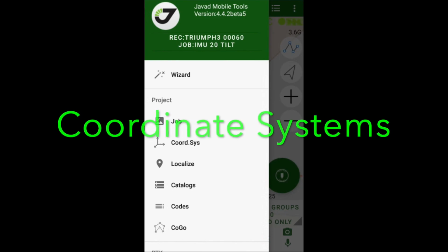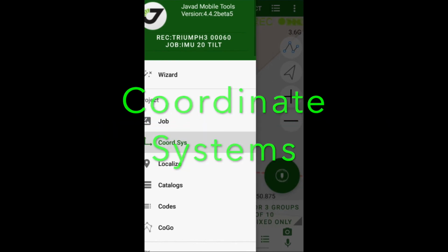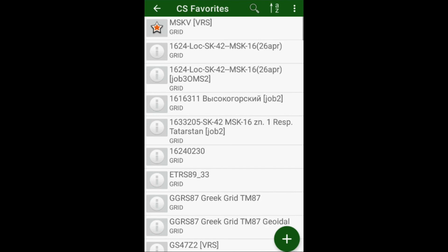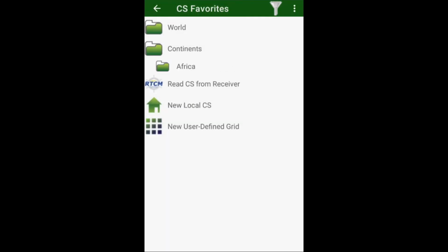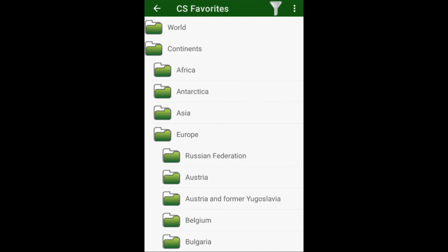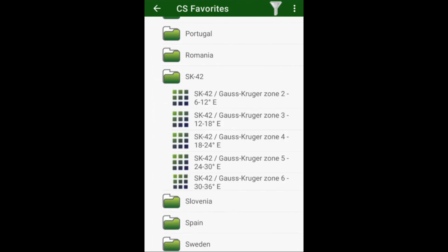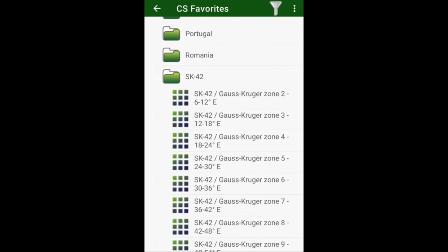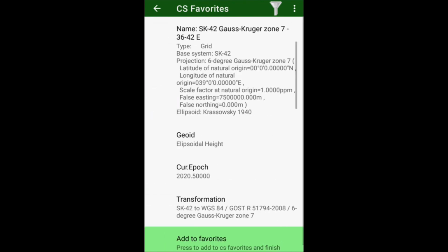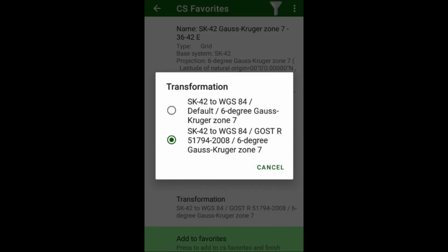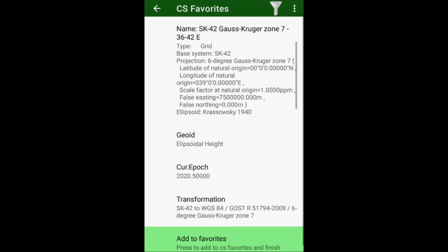The main reason for surveyor errors is coordinate system transformation. GPS works in WGS84, but results should be provided in a local coordinate system. There exist special techniques to fit WGS84 coordinates to correct coordinates. At first, the correct coordinate system should be selected. Please note that a coordinate system can have several transformations. A point converted with different transformations will have different values. Please check that the correct transformation is selected.